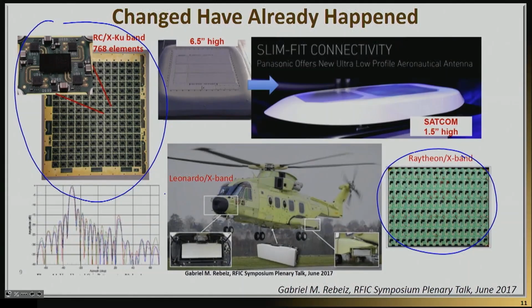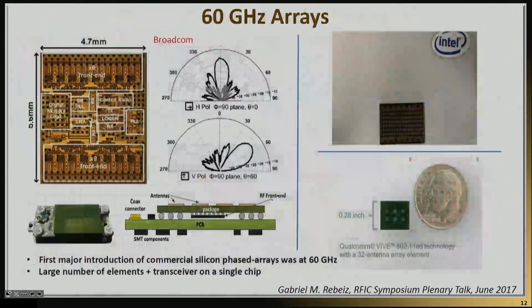Now, does it mean there is no silicon to silicon variability when you go from one chip to the next? No, there is quite a bit. But it is sufficient to basically make a large antenna array work. And so that's really the main reason that people are using that. Now, it doesn't mean that all antenna arrays will be uncalibrated. There are actually people who are thinking about self-correcting factors and self-calibration techniques. But in general, the amazing success of first-pass design basically makes this cost bearable by everyone.